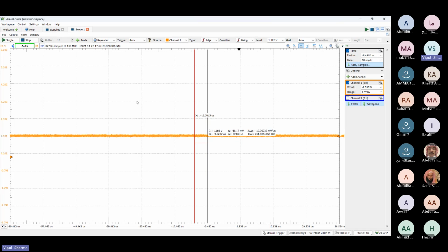So this kind of measurement which we did is just with varying the power supply. There are two other factors in PVT, as I showed: process, voltage, and temperature. We did the measurement using voltage variation, but process and temperature require other setups. For process, you need a lot of samples of this kind of chip, maybe 1,000 or 2,000 chips, fabricated on different wafers and in different lots, and then do the measurement on those and see if, from lot to lot or die to die or chip to chip, there is any variation in the performance of the bandgap reference circuit.